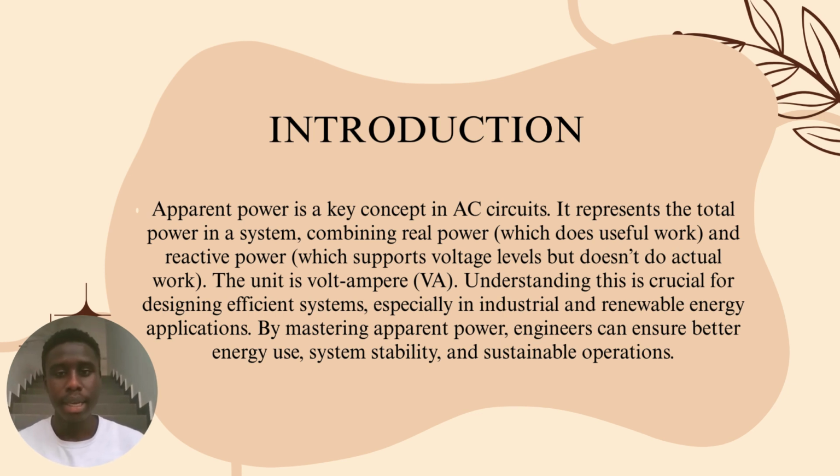Apparent power is a key concept in AC circuits. It represents the total power in a system, composed of real power, which does the actual work, and reactive power, which supports voltage level but doesn't do actual work. The unit is volt-ampere, VA.